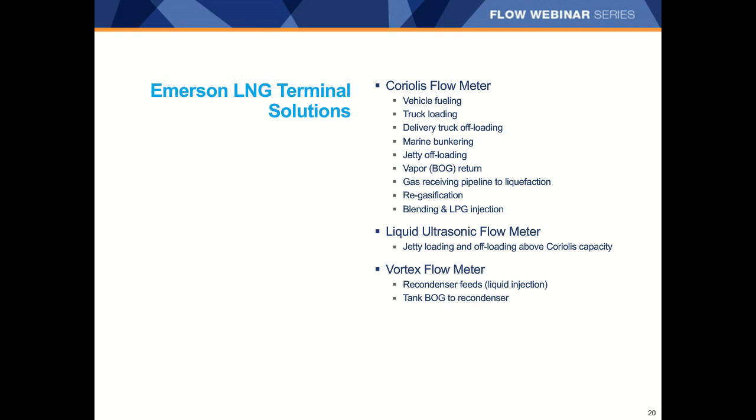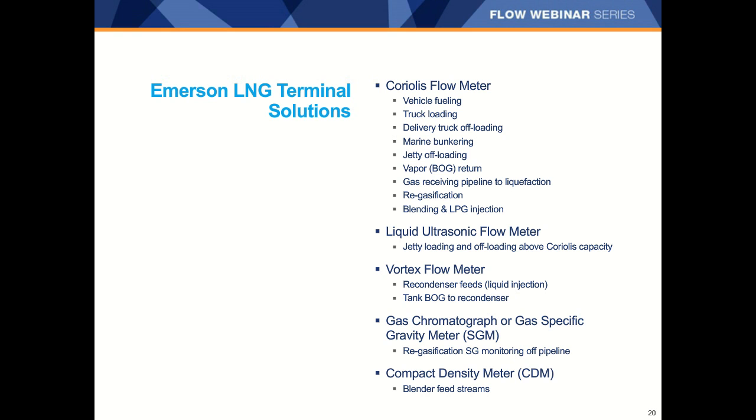Vortex meters have useful applications in LNG terminals as well. And Emerson offers gas chromatographs or gas-specific gravity meters that can both be used to monitor the heating value of the vaporized gas samples. A live density meter is available to measure blender feed streams.